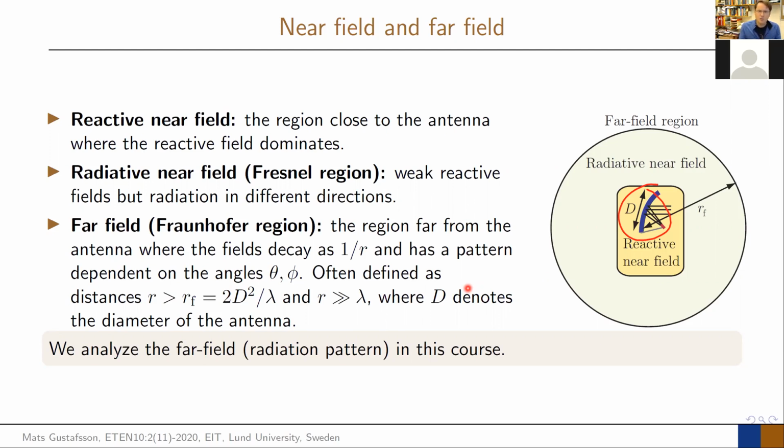And when you're very close to your antenna, you are in a region here which is called the reactive near field, this region here. And that is what you sit next to your antenna. That is what's happening when you take your cell phone and you put it next to your head. Think about your cell phone, you run it at say 1 gigahertz or 900 megahertz, you learn what the wavelength is for 1 gigahertz. How long was it? You all should know it, it's 3 decimeters. Which means that if I put my antenna here, my head is within 1 wavelength from this structure. That is called the reactive near field.